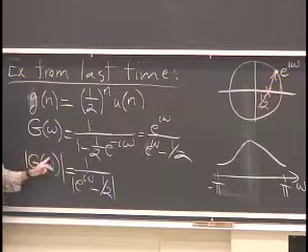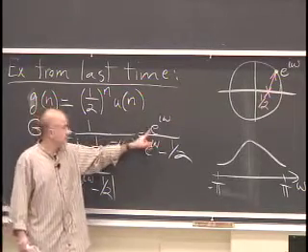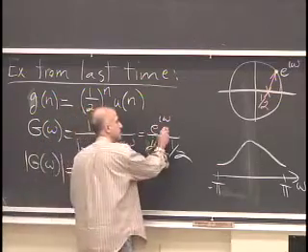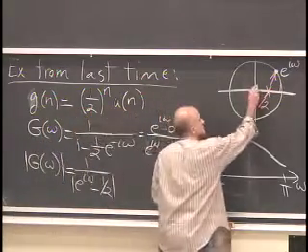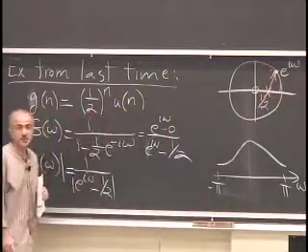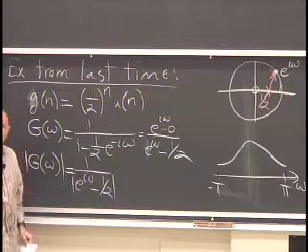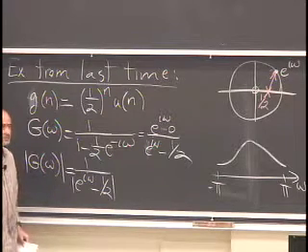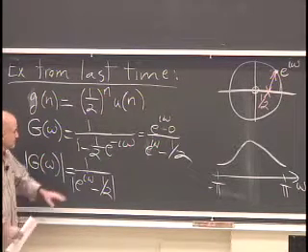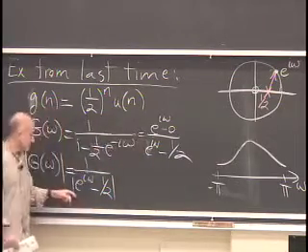So I take the magnitude of the frequency response. The numerator is 1. You can think of this as e to the I omega minus 0. So there's a 0 here with a vector going toward e to the I omega. But as I go around the unit circle, the length of that vector doesn't change. It always stays 1, so it doesn't really influence the magnitude response. And that's specified up here when I take the magnitude.